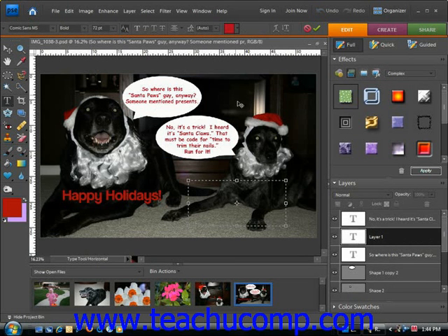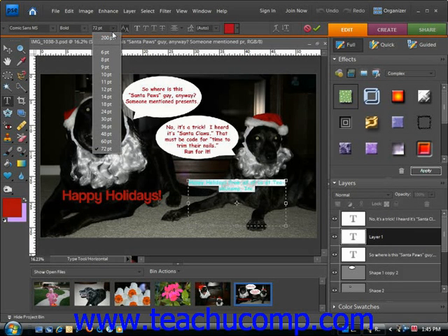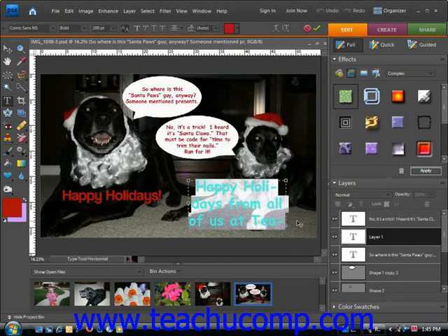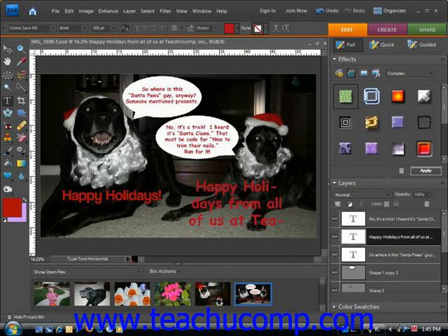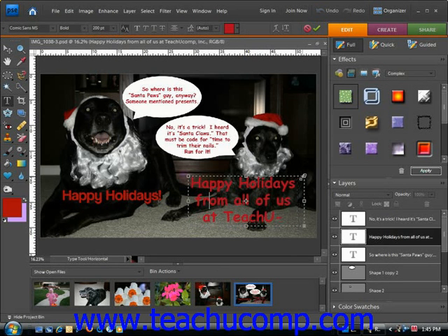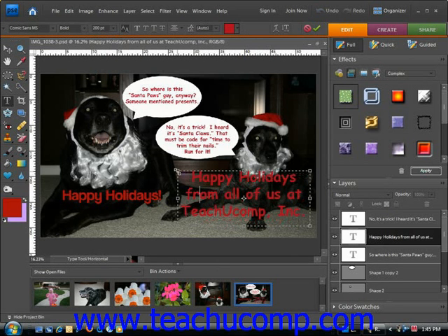So we can go into the bounding box and type in our text. Now you'll see here, let's go ahead and increase this font size. And here's what we mean, in that the text doesn't really look how we want it. So we're going to go in here into the bounding box and you can resize the bounding box until it fits your needs, just like that.